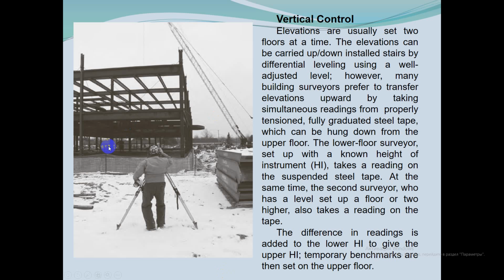The difference in readings is added to the lower height of instrument to give the upper height of instrument. Temporary benchmarks are then set on the upper floor.